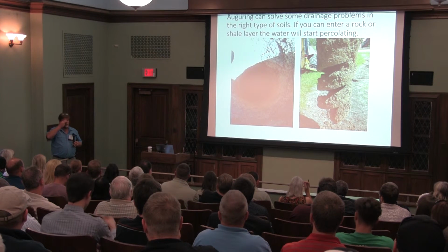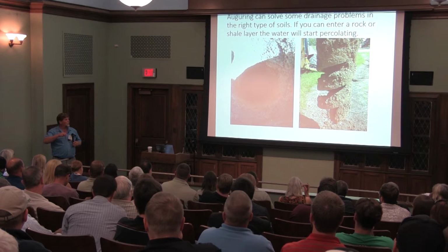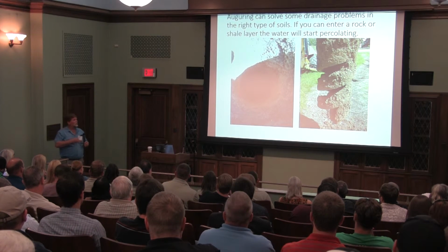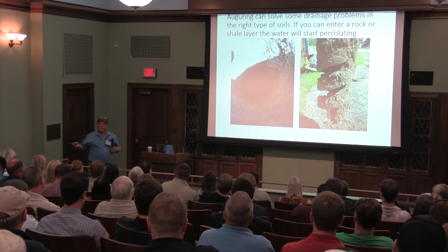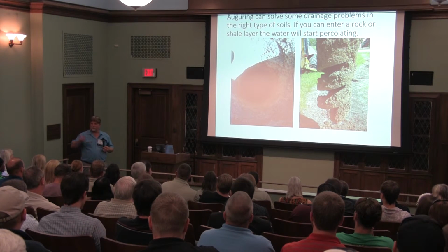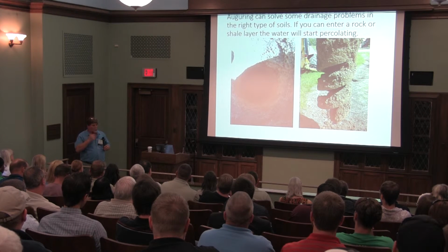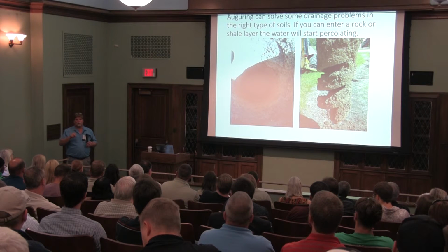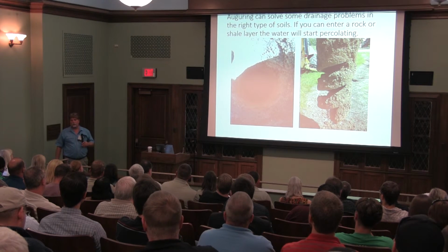We had, I can't remember now, many of these trenches, and they were all very long. Some of them were up to 200 feet long. They did one test pit on one side of the road and one test pit on the other. The state of Maryland's recommendation in their BMP manual is you have to do one test pit every 50 feet. Okay?